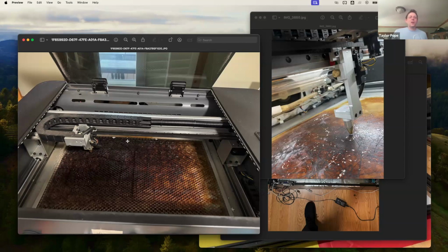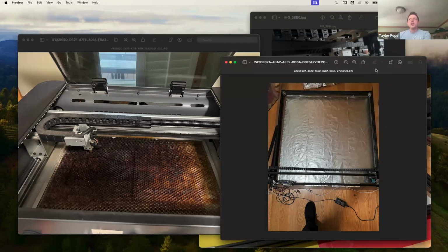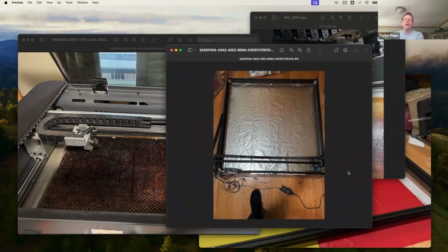The CO2 lasers are where I started off, but they're kind of the mid-tier of hobbyist lasers. The cheaper tier entry lasers are often diode lasers. Those are substantially smaller. They are more similar to the laser pointers you might have seen, but they're in a wavelength and a higher power that's more suitable to cutting. This laser cutter that I have is actually very large. This is a 1 meter by 1 meter gantry, but the laser itself is a small piece that the entire laser unit is moved around. That simplifies the machine substantially.